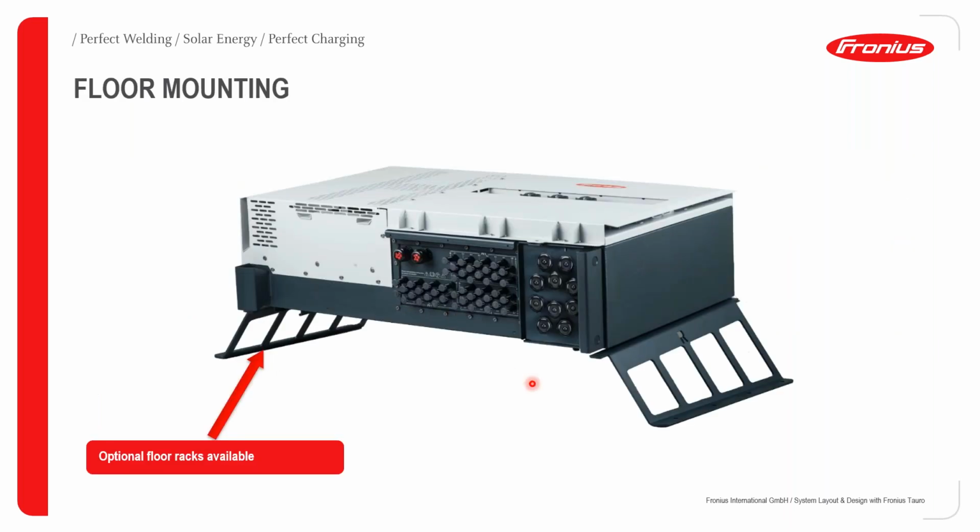As I mentioned in the beginning, we also have the possibility to do floor mounting with the Fronius Tauro. As we can see in this photo, we have provided some floor mounting racks, and this would allow you to directly mount the Tauros on the floor without any screwing. But then we do recommend, as you can see here, the mounting racks are actually a bit slanted. And then the perforations or the slots on the mounting rack itself would allow any water that would be running on this surface not to be blocked by the inverter, and therefore flooding issues are totally avoided by these floor racks.